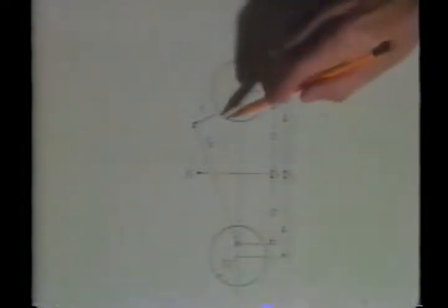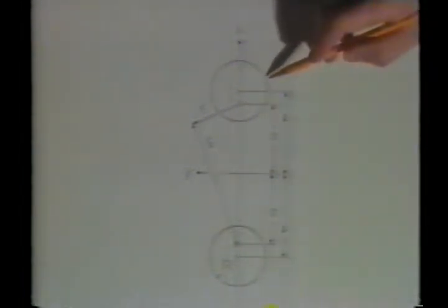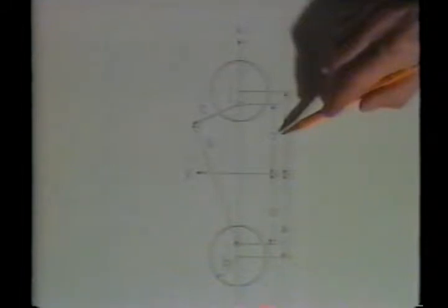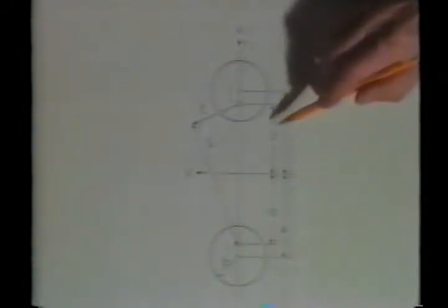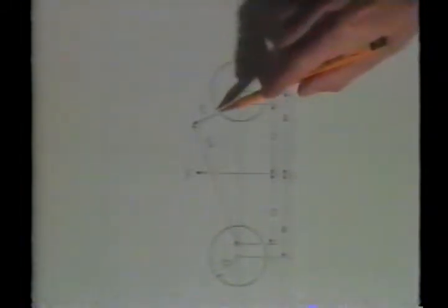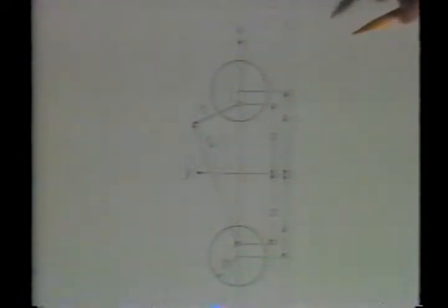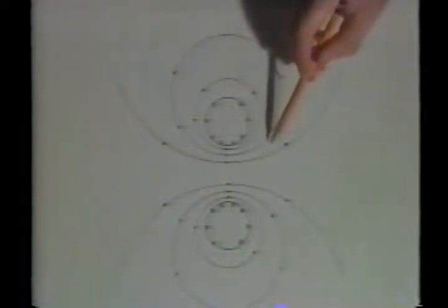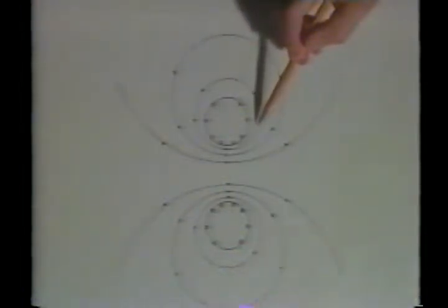The fields are terminated by surface currents in the cylinder and in the ground plane. The image line current contributes to the magnetic field above the ground plane in exactly the same way as the actual surface current, which is non-uniformly distributed along the ground plane surface.